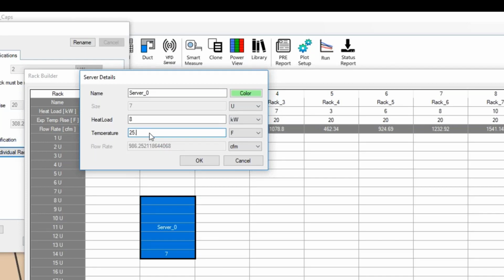The amount of flow, and here I'm assuming that it's uniform. In other words, if I move this to 9, it's going to go up linearly. And it doesn't go up linearly. But it's the best we have. This is really all we have without creating a function for each server. And the function for each server would have to be copied from the manufacturer, who's reluctant to give us their algorithm for adjusting flow rate as a function of temperature because it's proprietary. So to be honest with you, Geraldo, we don't know exactly what it is. This is the best information we have.